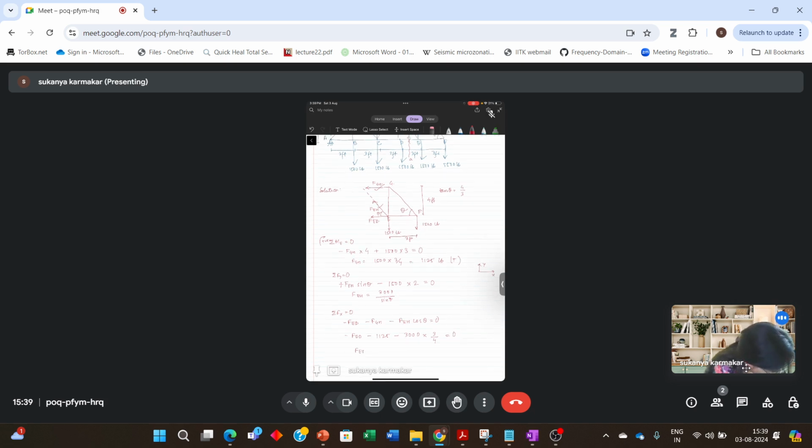So FED will come out to be minus 3375 pound, and it's negative, so the force is compressive in nature.